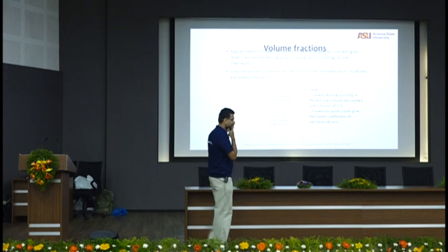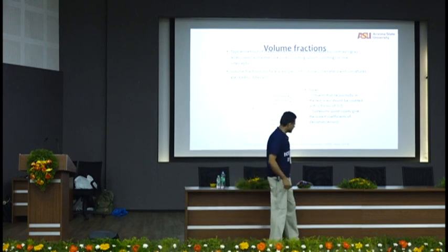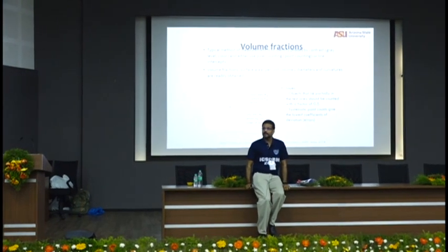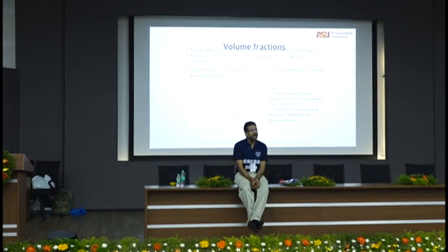I don't think you do it in India, but has anybody done air void analysis in concrete? Have you done any plain optical microscope based quantifications in concrete? No. Okay, so in the US we routinely do air void analysis because air voids are important for freeze-thaw protection. We have freezing and thawing in most places. So a plain polished section will be looked at under a microscope, and it used to be a very tedious technique. Now it's all automated. While I was a grad student, this was very tedious.